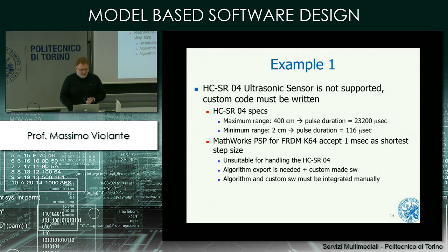distance. Well, if you look into the specs, you will see that this device is based on the time of flight of the echo that is generated by the object that reflects the ultrasonic pulse emitted by the sensor. And this echo gives rise to a pulse. The time duration of the pulse is proportional to the distance.